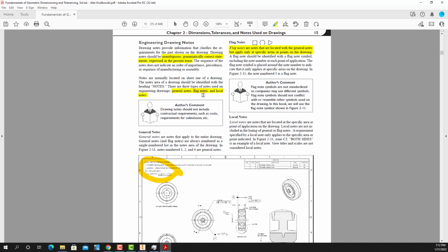And then point to that and have whatever kind of flag note that you want. And then in that note, you'll tell them exactly what font, what process, and what height. And then that phantom area, right? Or bag and tag it. If it's too small to be marked, they will bag it and put a tag on that bag, which we all get from Amazon daily.